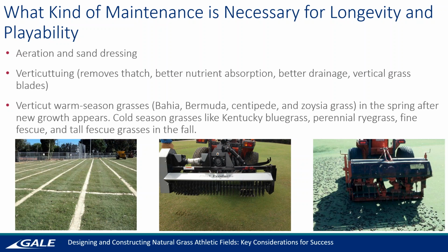And then on the far left that you see here is a show of the sand slits. Sand slits are a quick and easy way to introduce drainage flow patterns into your field, and to be able to get water off the field as well.